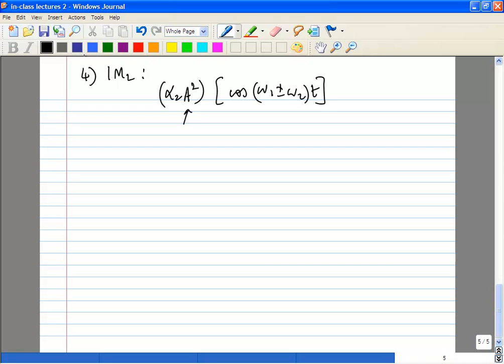There are also what are called homodyne receivers or direct conversion receivers. In these receivers you are directly converting the signal from RF to baseband. In that case, if you have any omega 1 minus omega 2 term, it could fall right on top of your signal and it could be a problem. So what you'll see is, if you have super heterodyne systems, IIP3 and IM3 products are very important, but if you have a direct conversion system, IIP2 terms are very important.